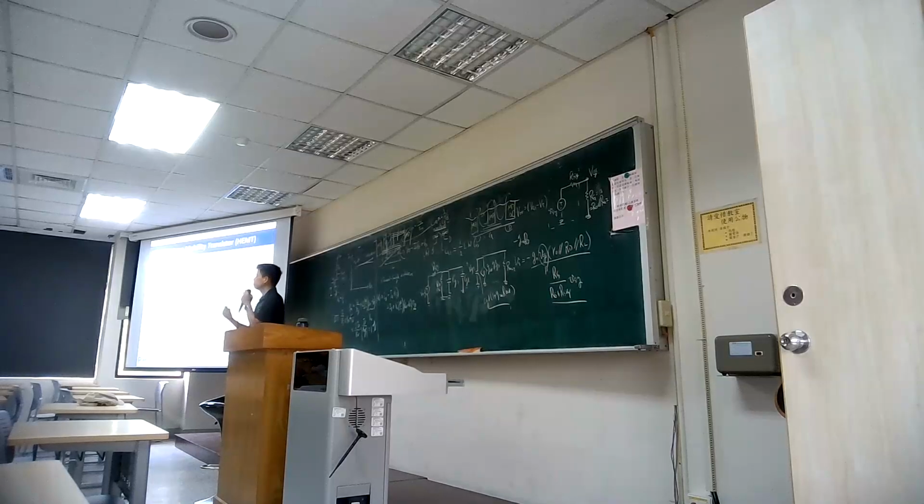So what is the benefit of this one? In the previous case, we tried to use doping, or the inversion layer, to increase the carrier concentration. But here, even without turning on the gate, there will naturally be a high density of carriers, which we can use to improve your current. So instead of using high-k or some fancy technology, we can try to get a really large population of free carriers, like a carrier reservoir. And then we can drive this two-dimensional electron gas in order to get high speed, and I think people also talk about high-power transistors.